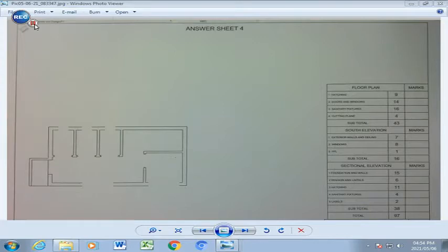Alright. And that means that we are going to put in all the windows in those spaces over here, properly done, and you will see how it unfolds in the drawing. And we will put in all the doors that we have here. Then we will basically hatch it as well, the proper SANS hatching, 2 lines and a gap and 2 lines and a gap. And we will also fill in all the sanitary fixtures in the designated area as indicated on the instruction page.